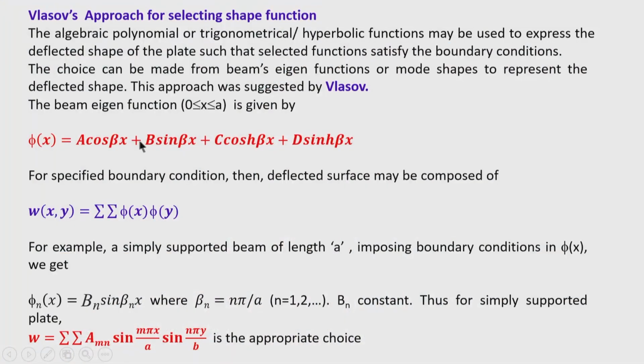So, the Vlasov approach for selecting the deflected function or deflected shape with a beam eigenfunction is also a very popular choice among analysts.